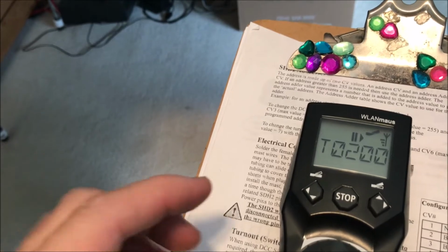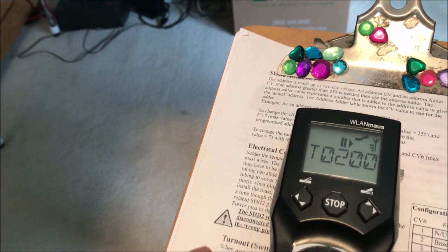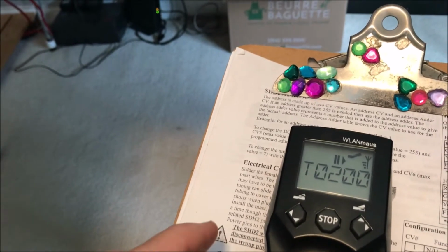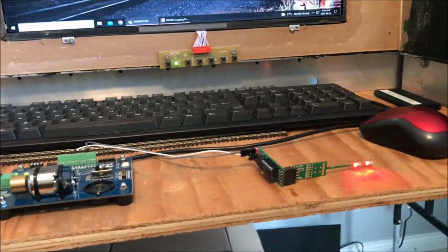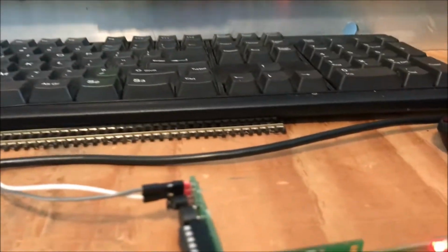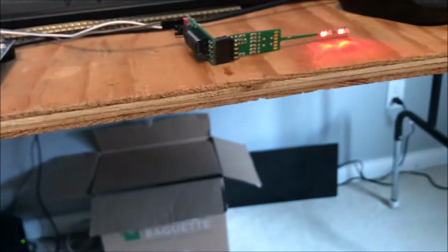So in this case, I would use signal addresses, and then I would use JMRI, and it would do all the logic. So you would say, under this condition, if turnout such and such was flipped, then this headlight should go red and green and so forth.